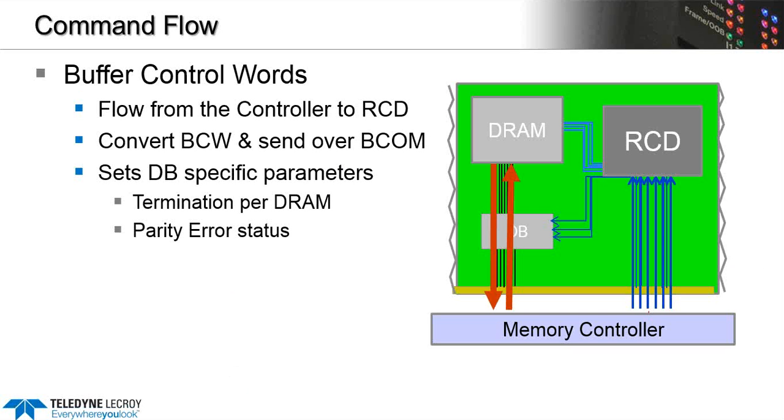Okay, so normal commands, your reads, your writes, your MRS, are going to flow directly between the host and the DRAM. So that's one point that shouldn't be lost on anyone. This is, again, how these LRDIMMs are going to decrease your loading and give you the higher capacity that they're promising.